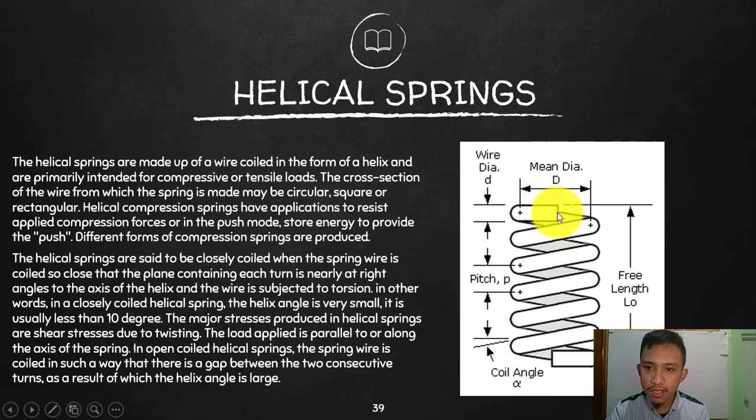To resist the tension, since the cross-section is not perpendicular to the load, the particles will experience a shear to resist the rotation of this spring, because as you try to elongate or compress it, there is this adjustment of your diameter here, and the adjustment will actually cause a rotation on the wire itself.